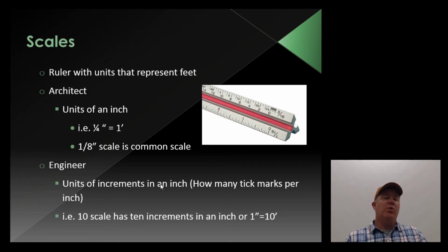So for example, 1/4 inch equals 1 foot. So 1/4 inch on paper is equivalent to 1 foot on site. That's the way I teach it. 1/8 scale is a common scale. In my classes, there are four major scales that we use. If we're using the architect scale, we're going to be using either 1/4 scale or 1/8 scale. There's going to be larger drawings.